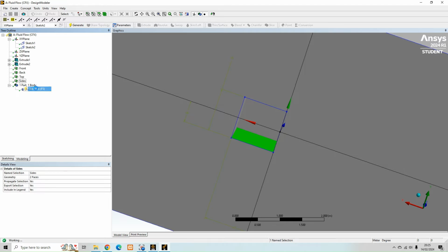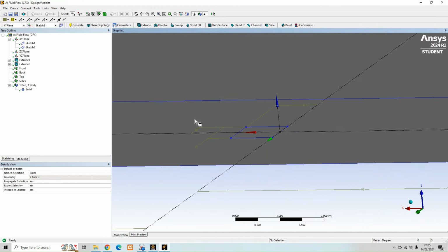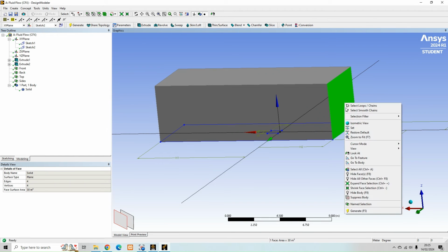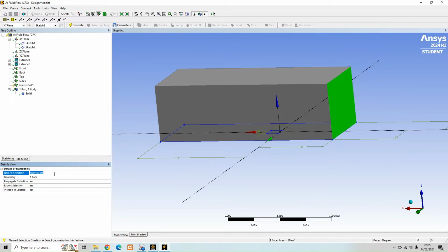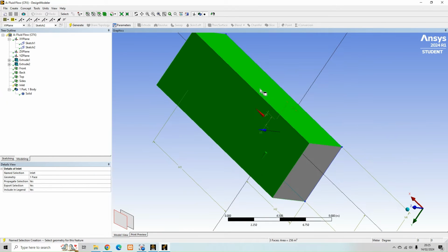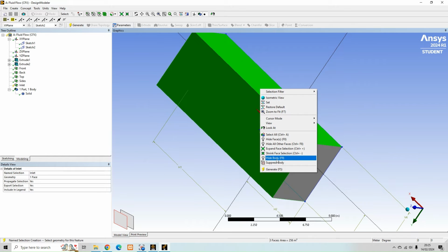And while we're doing this, I'm actually going to name the surfaces of the computational domain as well. You don't have to, there's no real need to. Just while we're in here, while we're doing the naming conventions. So that'll be inlet. I'm going to group these three together and call them slip walls because they're going to have a slip wall boundary condition.